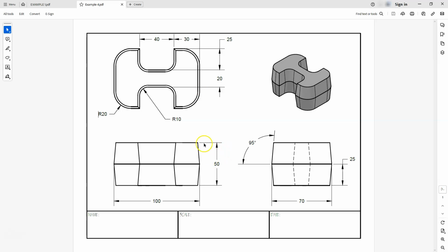But in actuality, when you're looking at this on the top side, you'll see that draft top surface and the bottom. But the way we have to approach this in Inventor is that we're going to create half of this, so we do have our 25 here. And then we're going to wind up mirroring this to get our 50. Our draft angle, that's going to be defined once we get to the extrusion, and everything else should be self-explanatory. So let's switch on over to Inventor and get started on this one.